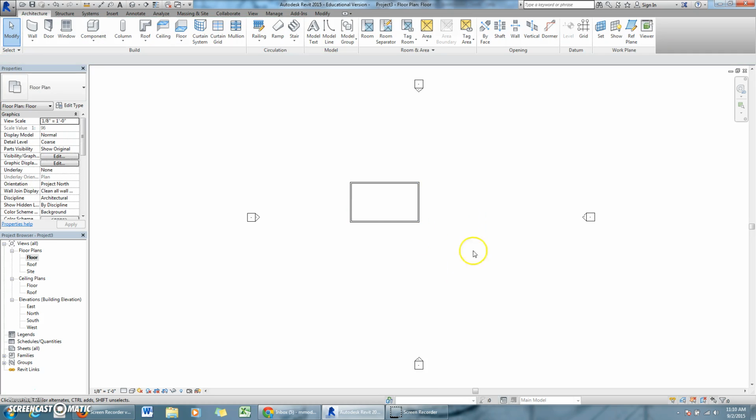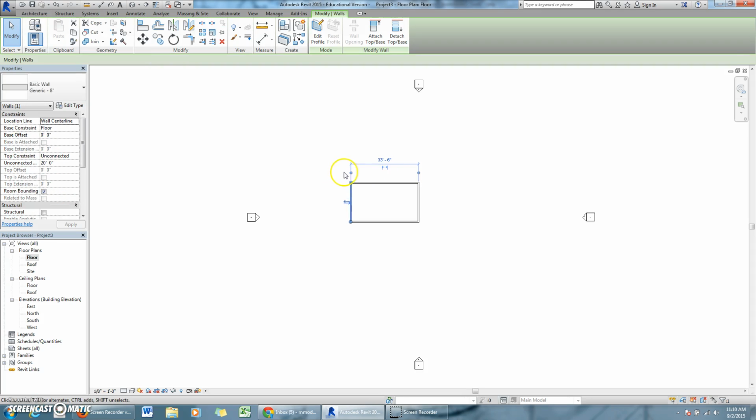So now we have our walls drawn, but they're not really of any particular size. To change the length of the walls, we're actually not going to click on the wall that we want to change the length of, but a wall that defines the length of the wall that we want to change. For example, if I click this wall, it highlights and brings up the length of this wall because it's defined by this and this wall. If I change that, I can click on this blue dimension, and we're going to change this to 16 feet.